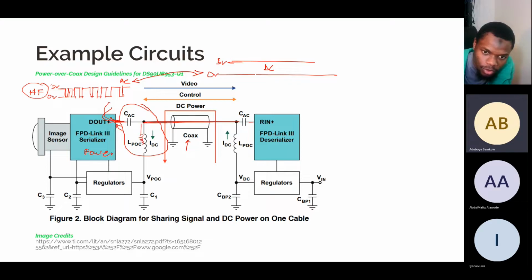What does an inductor do? Blocks AC current. What did you say? Blocks AC current. Exactly. So you are using this inductor to block the AC part of the current. So what you get at this point is no more AC, right? It's kind of like DC in a way, but it may not be super stable. So that's what you are using this inductor to do: block the AC, and then you get DC at this point.